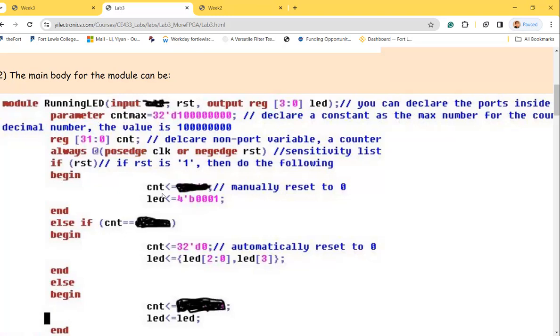So I think there's probably a typo in one of the instructions. You can try to use either RST equals 0 or equals 1 in order to trigger it. It's because when you are doing the switch, it bounces back and forth several times. It doesn't matter if it's a rising edge or falling edge. There's always an edge there, so it's detecting that and doing the updates. I don't think that really matters.